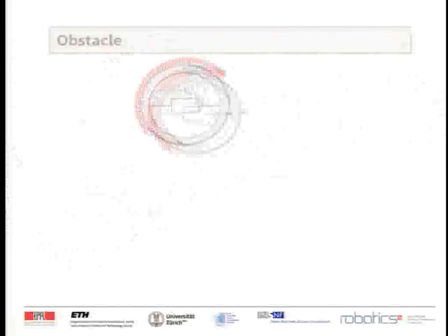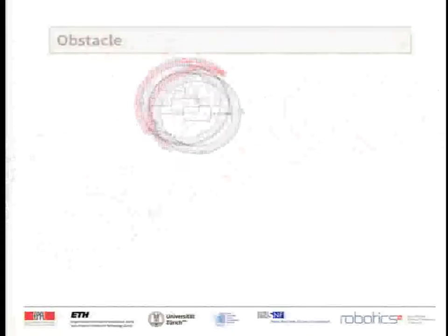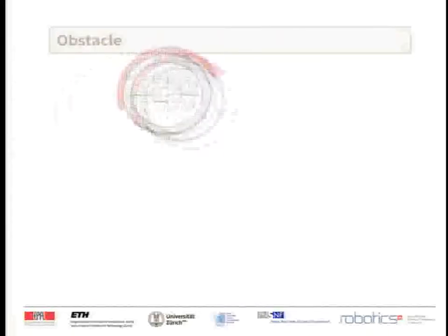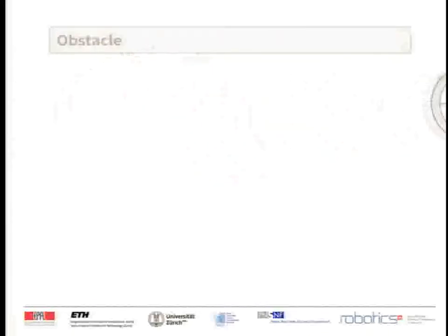And so we came up with a different design where we have a robot now which is embedded within a gimbal structure. This is a passive gimbal. So as the robot flies and it encounters an obstacle with the outer cage, the outer frame will rotate around the inner frame, and the inner frame with the propeller will remain very stable, passively stable. And this reduces the cost of transportation because your robot can just slide against the wall.